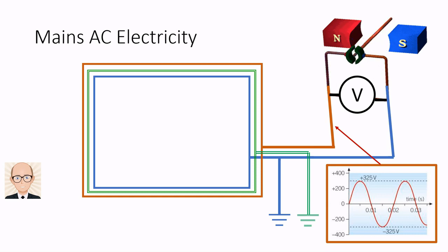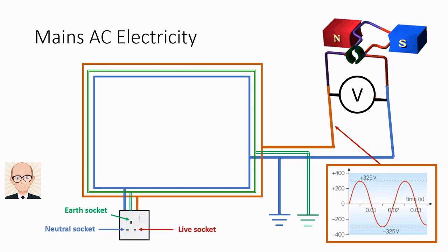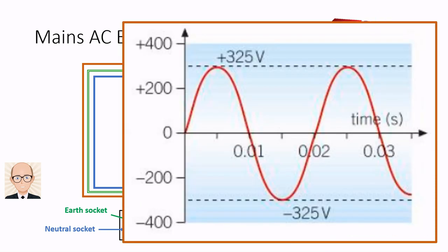If an electrical appliance develops a fault in which the live wire touches the outer casing of the device, you could be electrocuted if you pick the device up. However, by including a connection between the device casing and the earth, the current can flow directly to earth without going through you. The increased current will also be detected by an automatic shut-off device, which will result in the current being stopped.